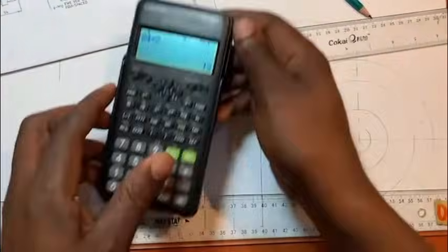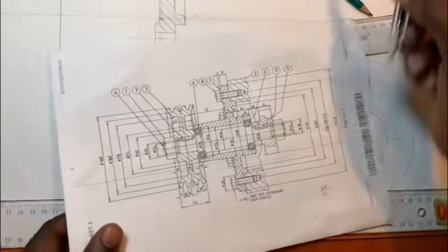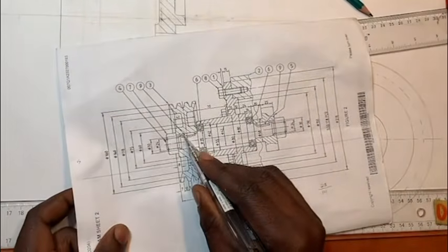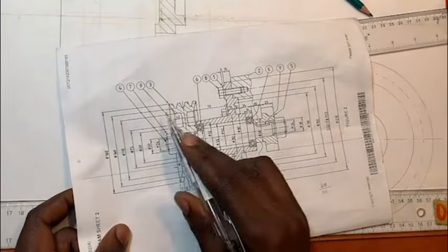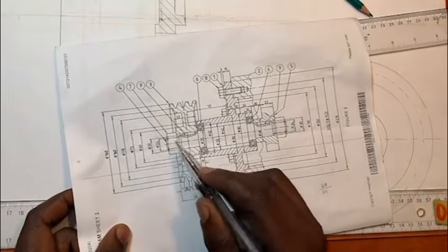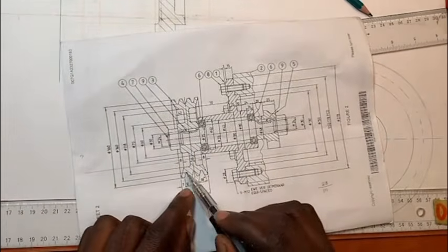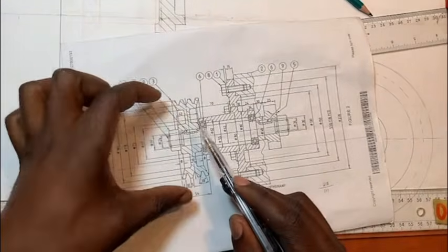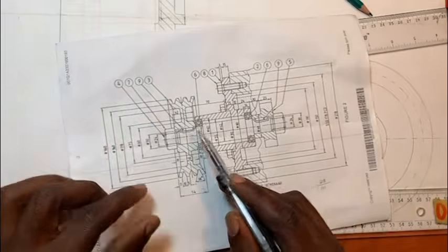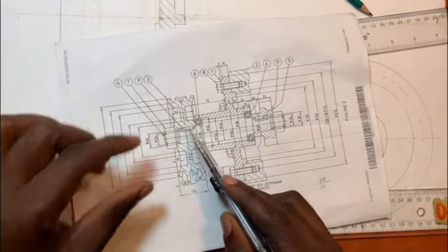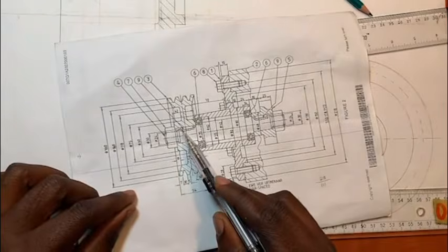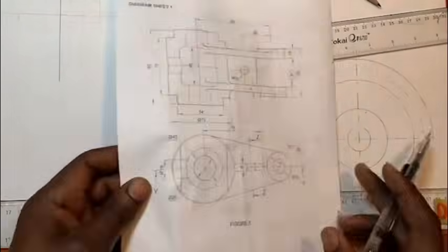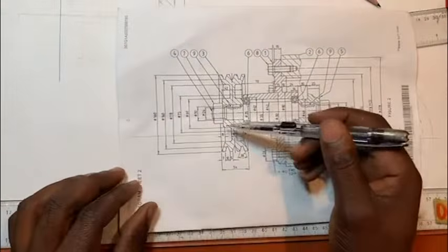So now let's double check that keyway, or we'll see it later. The key, which is item number 9, has to be stripped out. Item 7 strip out. Actually, in order for you to take item 3 out, you have to strip item 7, which is the nut, out, so that you can take out your item 3. And the moment you take it out, that key is going to be stripped out as well, which is item 9. Item 9 is the key. Everyone. Okay. Then, so what is going to happen now?